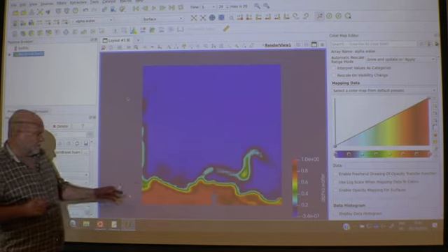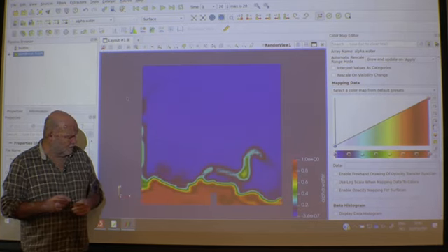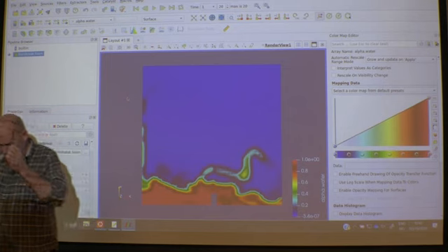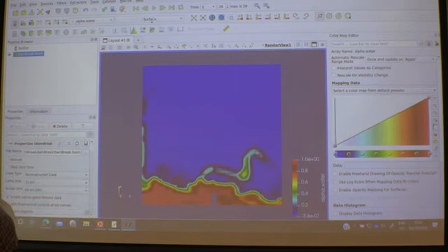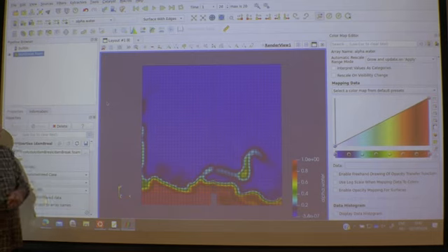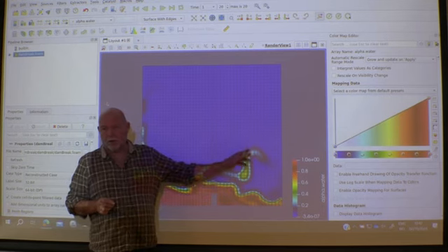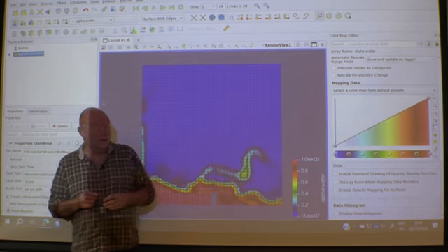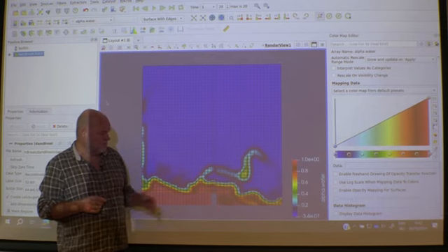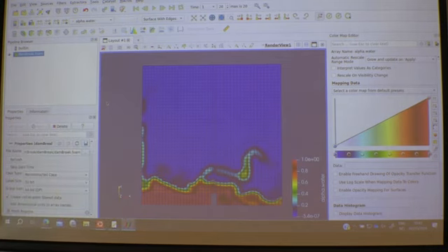The interfaces here, well, it's not perfectly resolved, of course not. We have a quite crude mesh here. So, as you can see, it's rather coarse. And of course, with this VOF method, you can't have droplets smaller than one single cell. You can't handle it. So it's definitely not the entire truth, but come on, it's a model and it works.